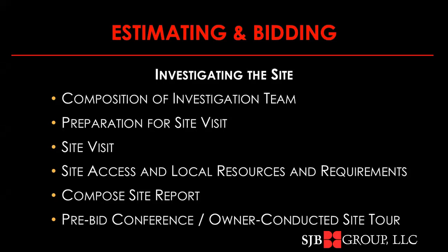We need to evaluate site access and local resources and requirements for the project. We need to write down what we saw in an orderly fashion. And we need to make sure we attend the pre-bid conference and any owner-conducted site tours.